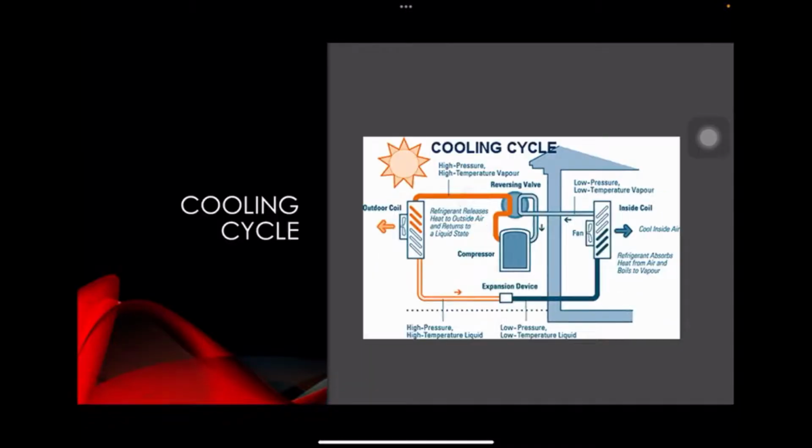And next is the cooling process cycle. In the evaporator, the cold refrigerant absorbs heat from the hotter chamber, causing the room to cool. The temperature is then raised by passing it through a compressor. It travels via the condenser coil where heat is transferred to the outside. To repeat the cycle, it expands to a lower pressure and cools down to below the room temperature.